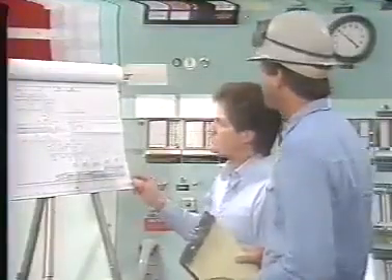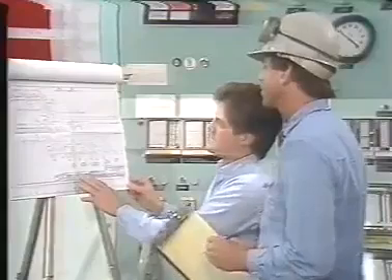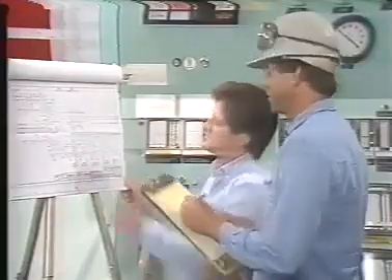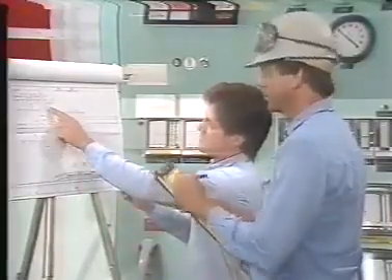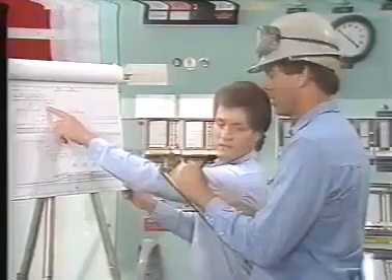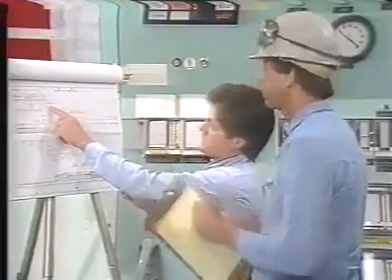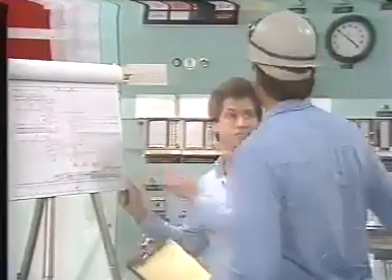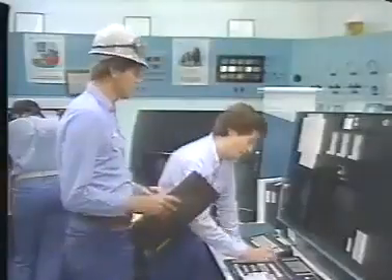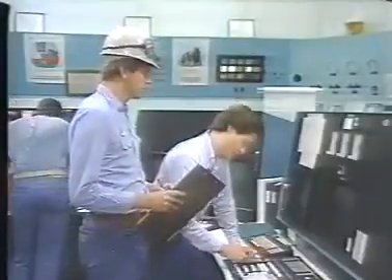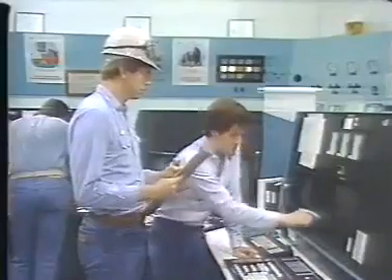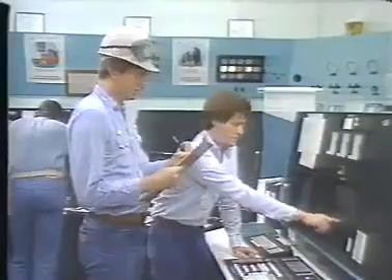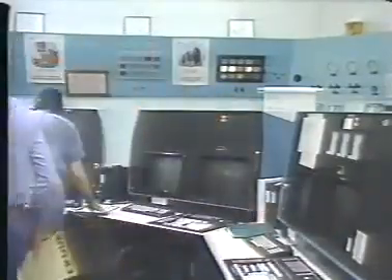Before correcting the operation, logically think through the problem. One way to remove heavy material from the top product is to increase the reflux rate. Another way is to decrease the reboiler temperature. In this example, you would probably decrease the reboiler temperature because of the energy savings. However, increasing the reflux rate may be the quickest way to remove heavy material from the overhead product.